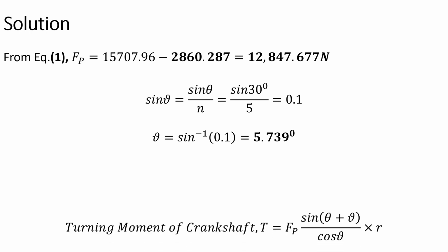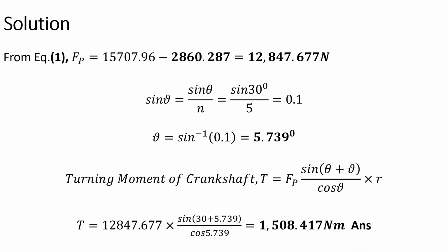Now we are able to calculate the turning moment of the crankshaft, which is given by equation 3. After plugging in the values, we get the value of the turning moment as 1,508.417 Newton meter, and that is our answer.